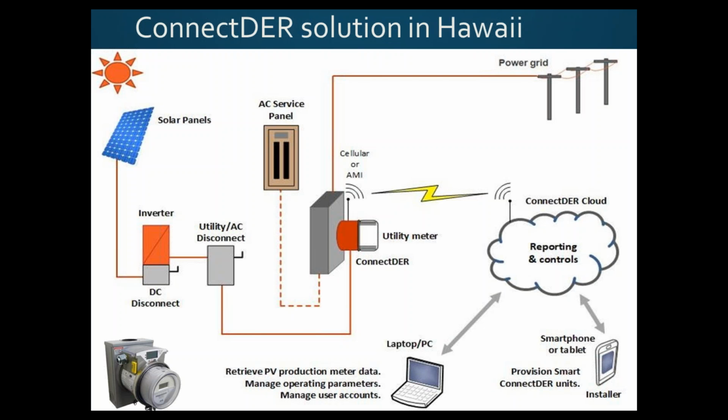Now that said, that's only half of the story. Interconnection is great, but if everyone could just interconnect very easily, you'd end up with the same issues we talked about earlier. So we layer on top of our basic model revenue grade metering for the PV and for the whole house, relay controls on the PV for blunt force curtailment on a very limited basis, and ultimately an Ethernet bridge between the Connector product itself and the inverter. In addition to lowering the cost of interconnecting and integrating solar, in the longer term we want to create a simple plug-and-play conduit between those inverters and a back-end system of addressable assets that the utility system can tie into and begin to create compensation models for those inverters automatically. Next slide.